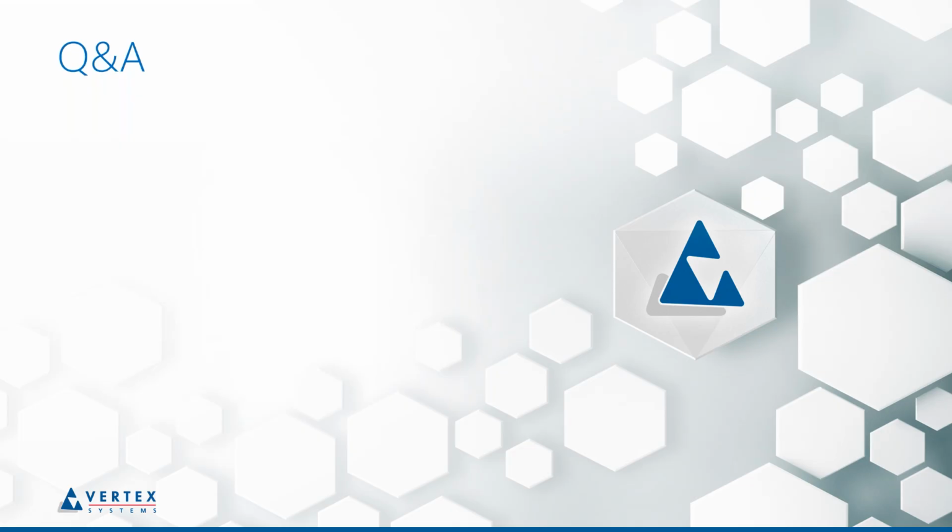Okay, so any other questions? Here John wants to ask also, what if we want to break walls at sheet joints? What was that again? Break the walls where? At sheet joint. Oh, that's where I was showing in the video. That's where I like to do one big panel, generate the sheets so you can see where the sheets are, and then use that manual break. We don't have a function that's going to do panel breaks where they should be before you've generated the studs and sheets, etc. So I sort of use that two-step process. Thanks, John, for your question.